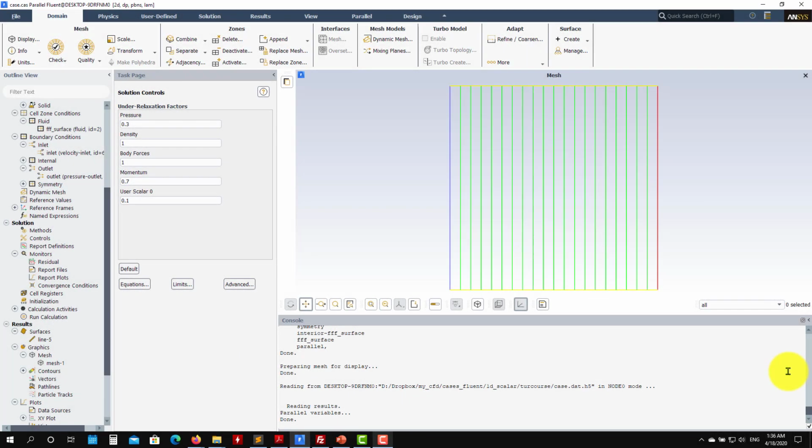Okay, let's address now the issue about under-relaxation factors and what they are. I mentioned this is something mainly related to steady simulations, but you can also put it in on an unsteady one. So we're going to work in this case. It's a very small mesh. Actually, it's a 1D case. When you open Fluent, you open it as a 2D mesh and we'll get 1D.